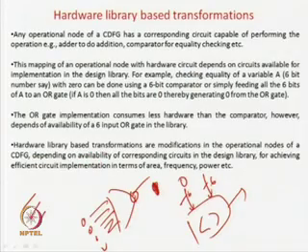What is the better thing is that if you use a comparator, then the comparator actually uses a lot of XOR gates for computing. So, what does that mean? Say 2 3-bit numbers are there, say this is A0, A1 and A2, and the other 3-bit number B0, B1 and B2. The 2 3-bit numbers have to be compared for equivalence. So, what you do is XOR A0 with B0, A1 with B1 and A2 with B2.